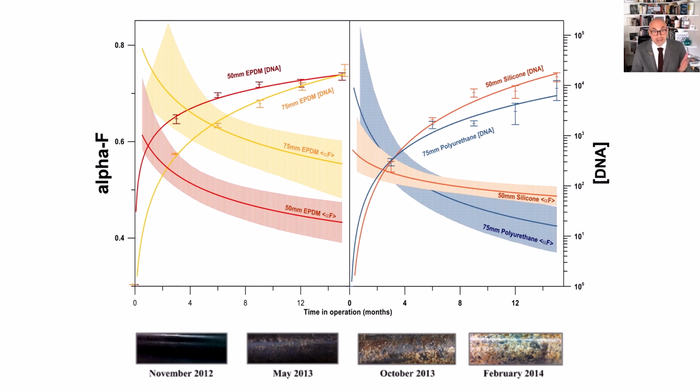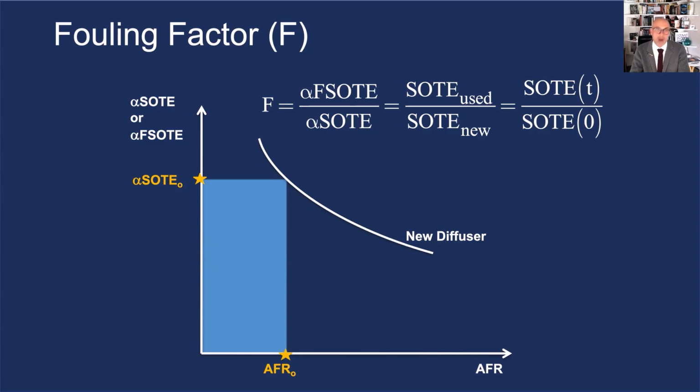So the efficiency in a year and a half could be as low as half of what it was a year before. So half the efficiency means more than twice the air, because if you put twice the air, well, first of all, the air comes out with larger bubbles now, so it's less efficient in terms of SOTE. So all of this is linked. Alpha and SOTE. So with less and less efficiency due to fouling, you need way more in proportion to compensate efficient airflow, okay, on the other side, which means more kilowatt, more cost.